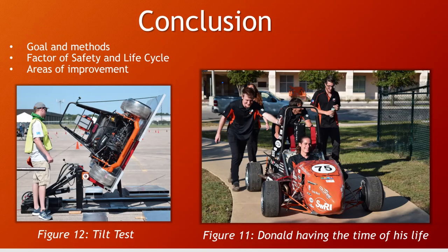This report analyzed the rear suspension of an FSAE car and showed there are many areas of improvement, both to weight reduction and more efficient use of the material of the beam. We used matrices, Excel, equilibrium equations, and SolidWorks in order to show this. Our factor of safety for the beam was found to be above 2, and the factor of safety for the links and bolts is currently at 3. The expected life cycle is 250,000 at the worst case loading scenario.